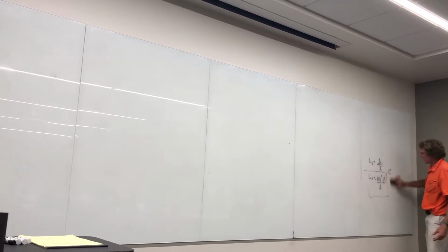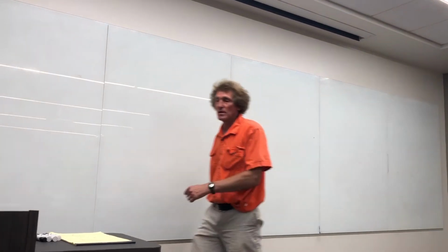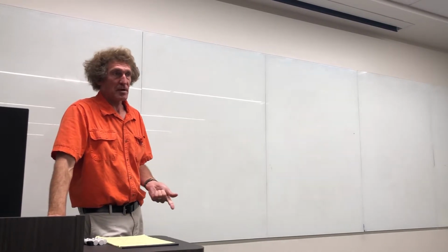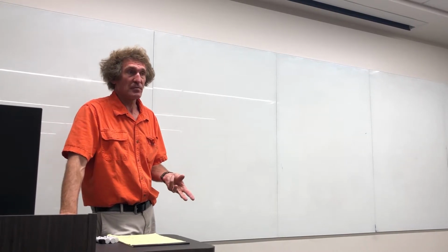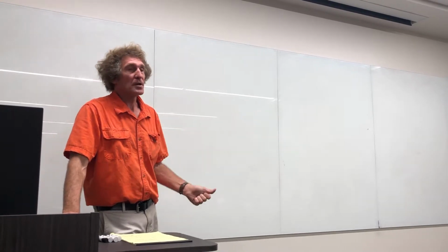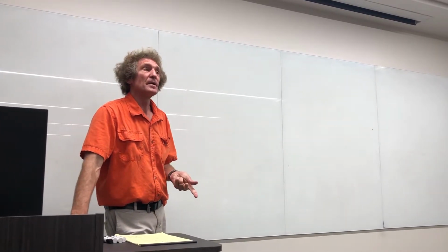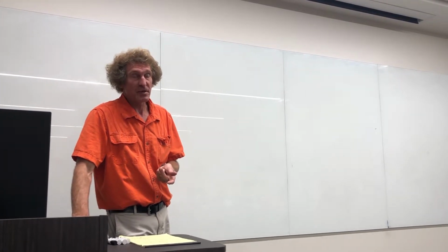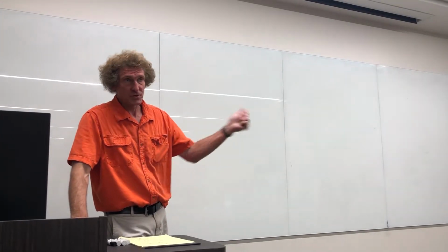Contrast this stuff. How did we find capacitance or resistance for any system? What did we do? We had to assume something, right? For resistance, we usually assume current, right? Then from current, we got J, right? And after J, we got E. And then we integrated E dot dl to get V, and then we took V over I to get R, right? There was an assumption. First thing is assume current. If we wanted capacitance, we usually assume charge. Then we got the D field, then we got the E field. Then we integrated E dot dl between the plates to get V, and then we said that capacitance was equal to Q over V, right? So we assume charge.